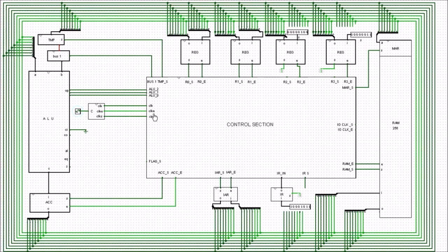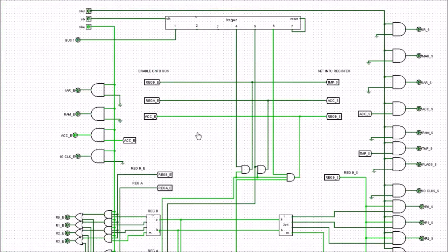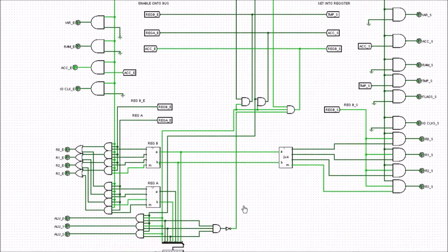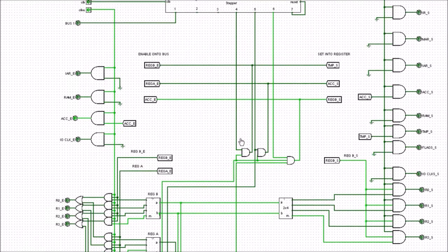So that's our clock enable gone high now. And let's have a look and see what it's done in the control section. So the clock enable has gone high here, and we've got an ALU instruction, and there's one other section here which comes from a compare instruction, but we'll talk about that later on, so there's no need to bother about this bit here just right now. So this has gone high, so it means that we've got two other things happen.